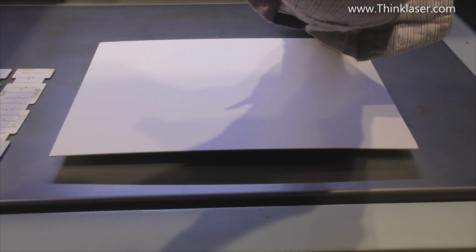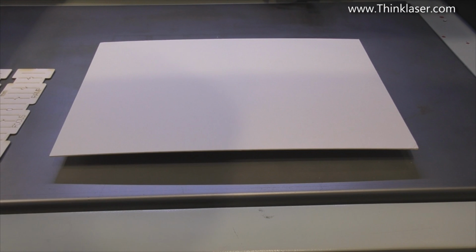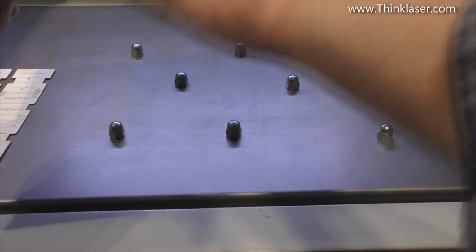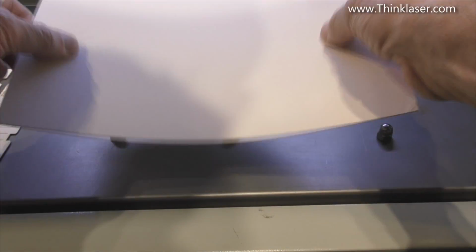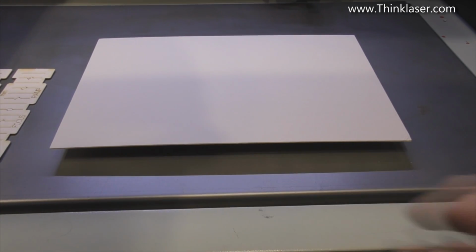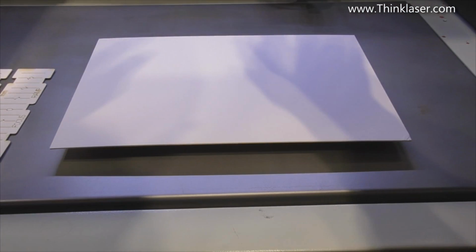First of all, if we turn the air assist off, which I have done now, the problem is that we're likely to smoke the lens. So what we need to do is to make sure that we've got lots of airflow passing across the job so that we don't stand any chance of doing just that. The way that we're going to achieve that is by dropping the table down a bit. The first thing I've done is stop the rubbish from collecting underneath here, so we should finish up with a clean surface underneath. And now what we want is airflow passing underneath, a small amount, but we want a lot of airflow across the surface.